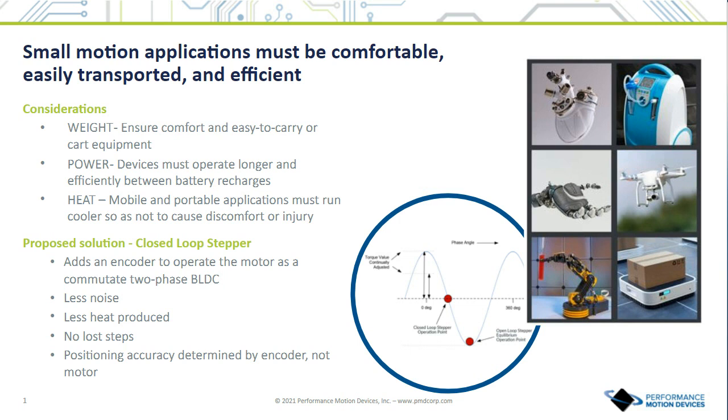So we're starting to see more and more closed loop steppers in certain applications where they want the cost lower, where it's an end consumer application in the medical space, but they still want the higher performance, they would do a closed loop. So typically, the controllers we sell are fully integrated, and you start getting to use more of the advanced control techniques like FOC, current control, path planning, and stuff like that too. And all of this, the main idea is you're trying to get it to operate at its sweet spot for the motor, so you're getting less noise and fewer lost steps.